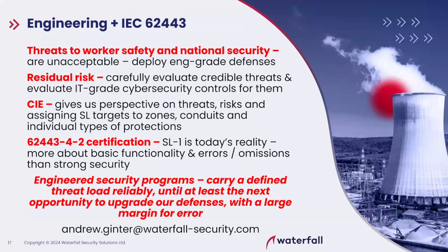And so the question is, how thoroughly do we have to protect the safety systems? And the answer is, it depends on the adversary. So if all we have is firewalls between the internet and the safety system, and you can pivot through one firewall after another, the bad guys can get into the safety system and mess with it, that's unacceptable. Every engineer out there will say that's unacceptable. You have to put engineering grade protection in there to prevent compromise of the safety system, unless you have electromechanical safeties after that as well.